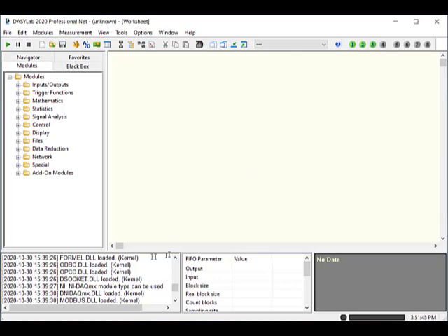The bottom of the DASYLab screen includes information for diagnostics. The lower left is referred to as the console window. This initially starts out with a list of the files that DASYLab loaded when it started up. And for example, you can see the last two files. One of them is the data translation library, and the other one is the measurement computing library. The rest of these are available. It's diagnostic mostly. You're not typically going to look at that unless you're having trouble loading a driver.